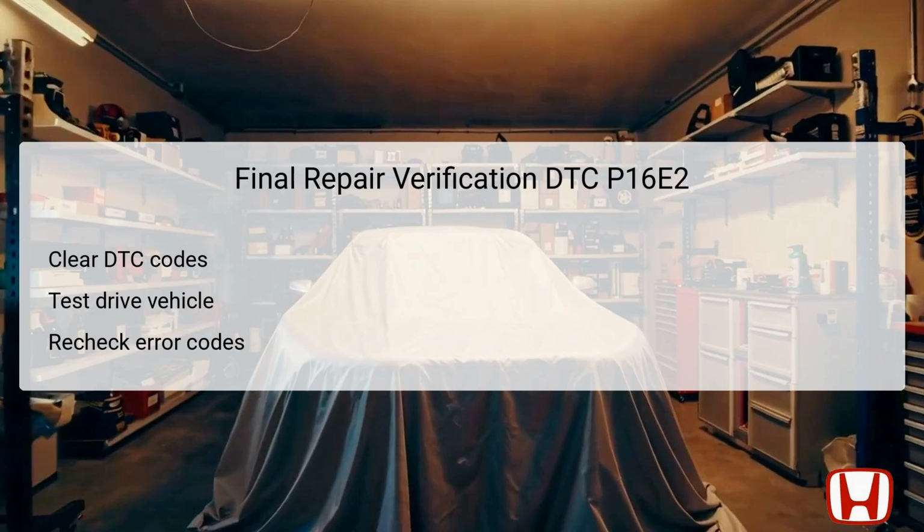After conducting repairs related to DTC P16E2, perform a final repair verification process to confirm that the issue has been resolved. First, clear all stored DTC codes from the PCM, and then conduct a test drive under various conditions to see if the vehicle performs normally. After the drive, recheck for any new or reoccurring error codes. It's vital to ensure that the communication between the PCM and the alternator is restored. If the DTC P16E2 reappears, further investigation will be necessary. This step is crucial to confirming that all repairs were effective and that the electrical system is functioning correctly.